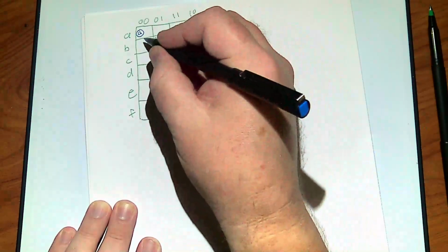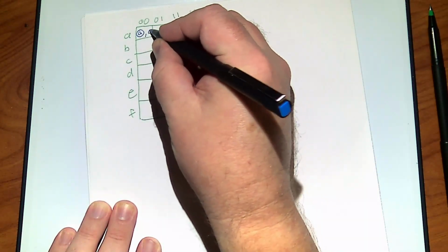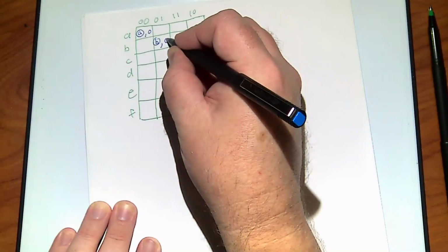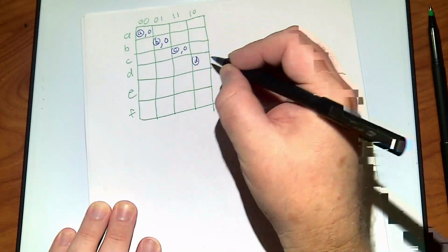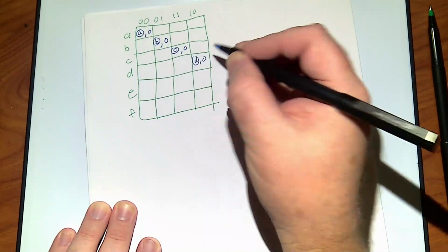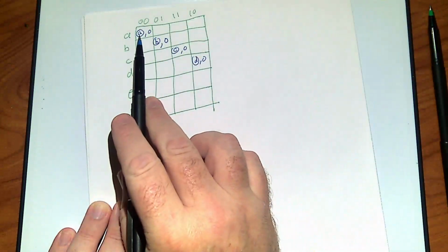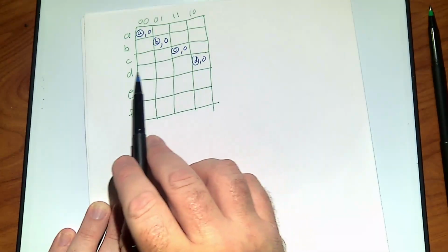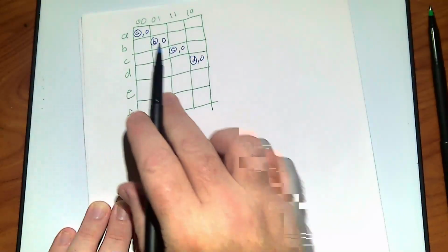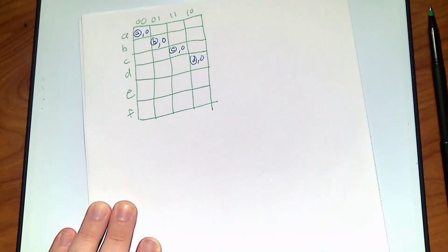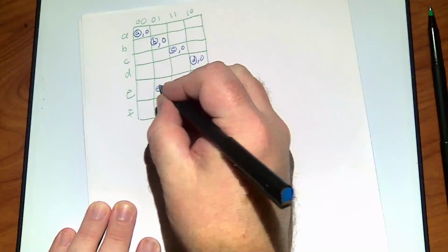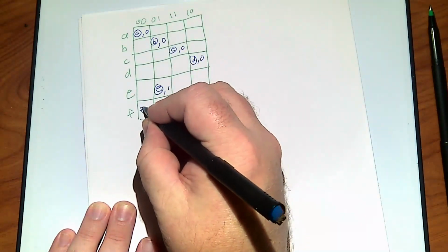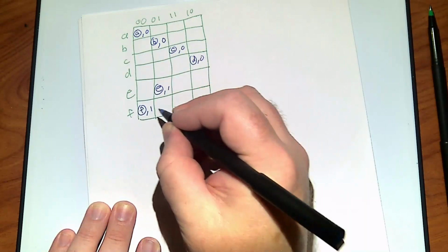Now, I'm going to use a slightly different convention here. I'm going to put my outputs after a comma inside here; you could make it after a slash. It's not a huge thing. So let's just say I have these, right? This is my state A, its output is 0. B, its output is 0. C, its output is 0. D, I'm not telling you what's happening in the other cases. These are stable states. They just hold where they are. Let's say E, let's put it here, and maybe it's outputting 1. And I'm going to make F stable everywhere.